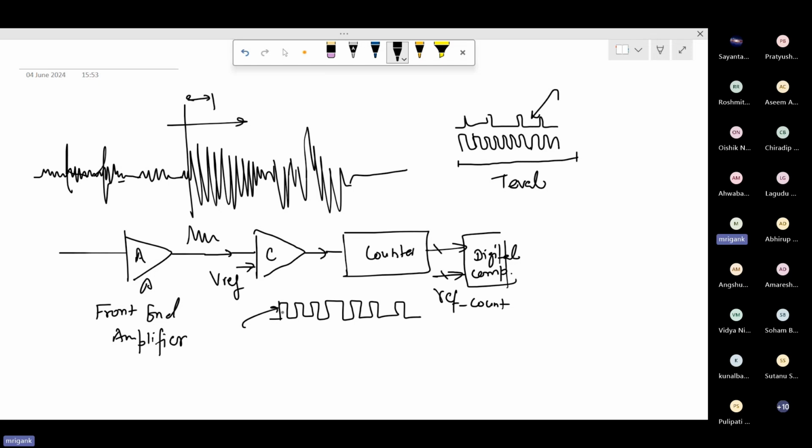What is the rationale of using that? Are you getting the point? Because if you zoom in on this portion, it will be something like this and this. We are going to apply this to the control voltage. What will happen? The oscillator will oscillate here. Again, stop. Again, oscillate here. Stop. What are you going to get from this? So there's no point of putting a VCO. Are you getting the point? Why are we putting a VCO? Yes, sir, yes.